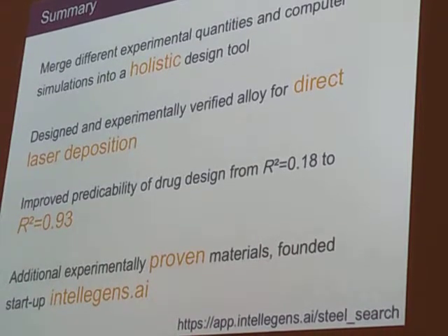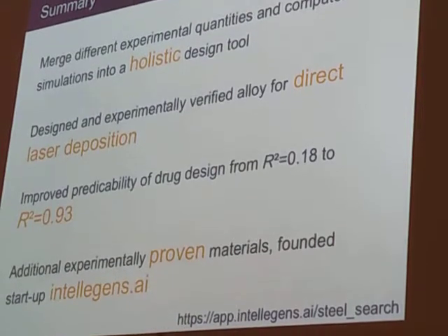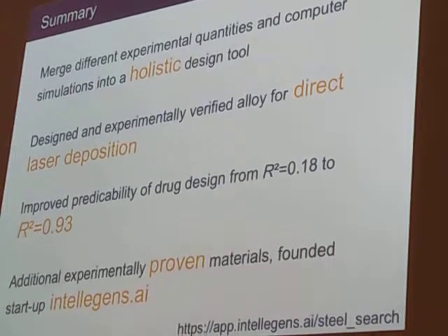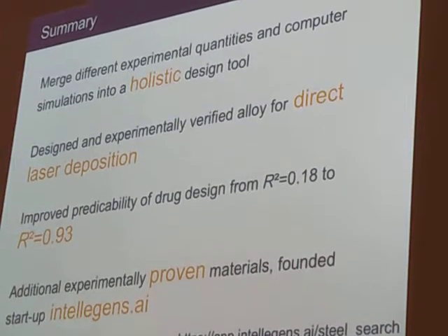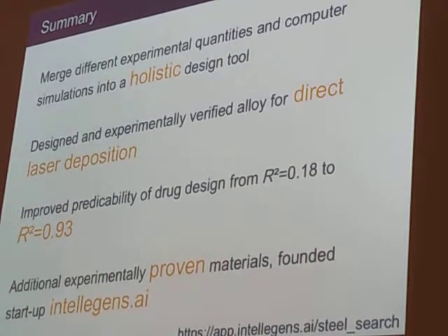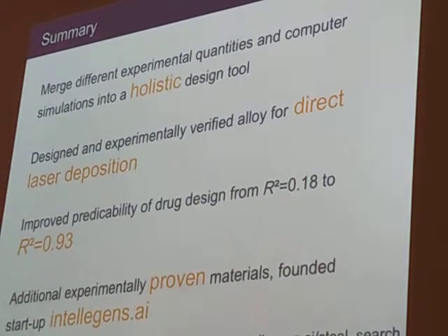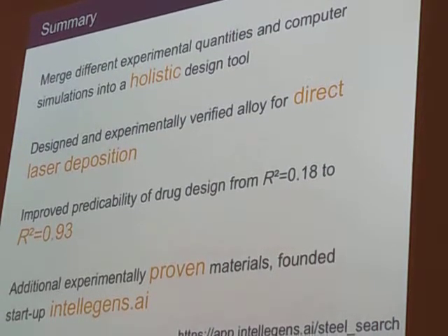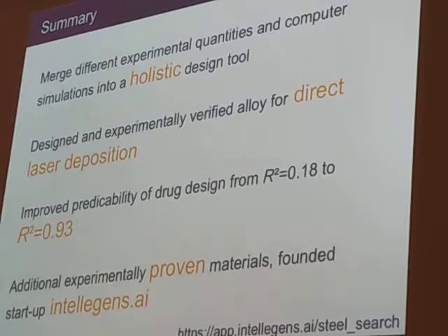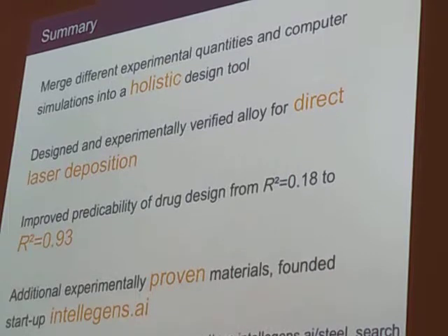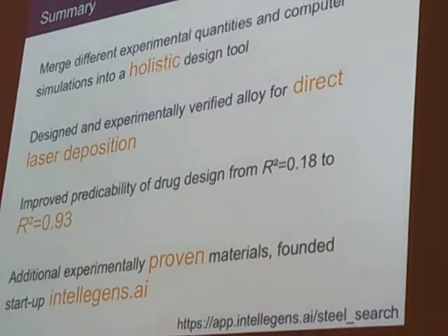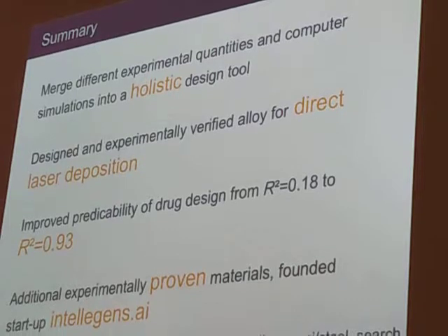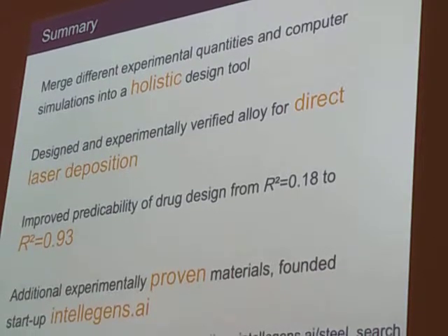I don't see that. Well, we've got to be able to find the right compromise between all of those material properties. If you just want to find something for welding, you can find it. If you want to find something good at 3D printing which is similar to welding, you can just print it out. But there are always other problems like that. C263 had terrible or not good enough oxidation resistance. So what we're doing is interpolating between lots of different properties, getting the compromise right between all of them. We wouldn't be able to go off and find the highest melting point material ever, because we'd be dramatically extrapolating and then it won't work very well. It must always be interpolation.